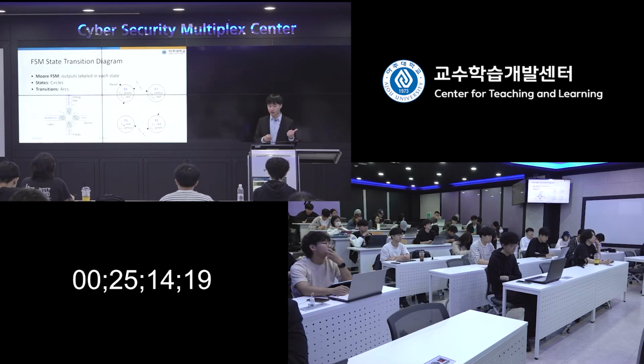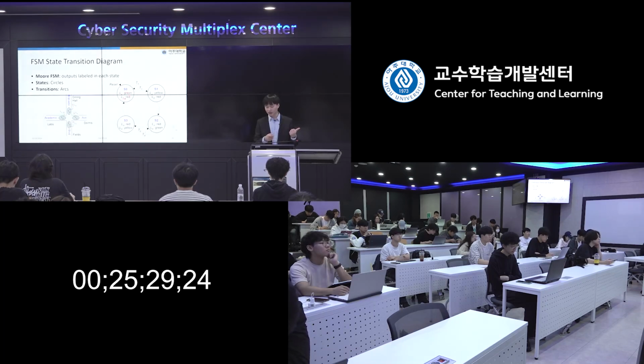Then you move to state S3 and switch LB to yellow. Then after 5 seconds, S3 will switch back to the initial state, which switches LA to green and LB to red. So this is the state transition diagram we built based on this problem setting.